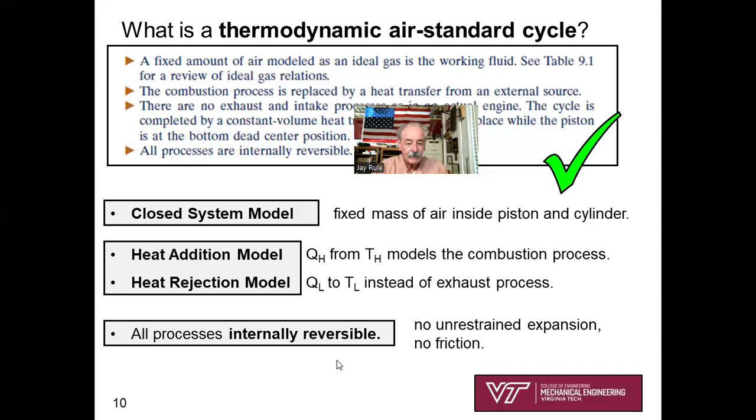Let me repeat this slide. For our air standard thermodynamic model, we're going to have a closed system, heat addition instead of combustion, and heat rejection, QL, instead of exhaust. Also, each process that we describe is going to be considered internally reversible.